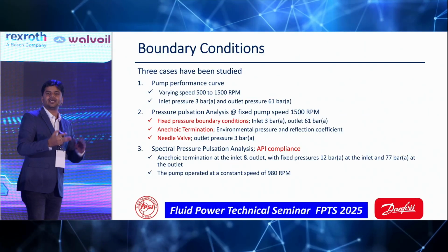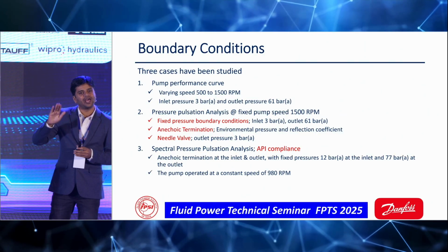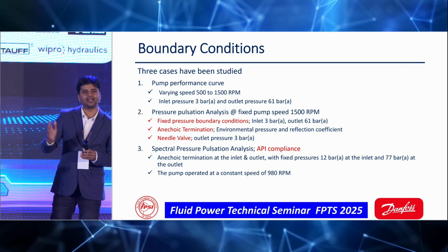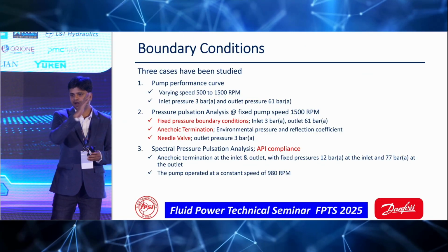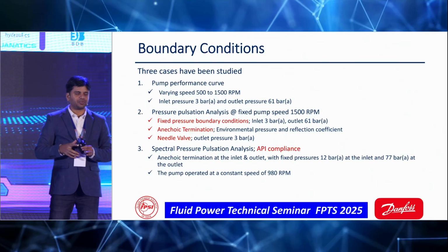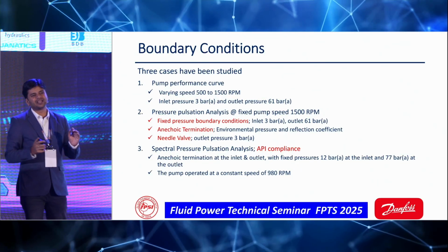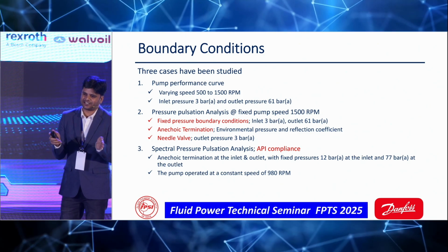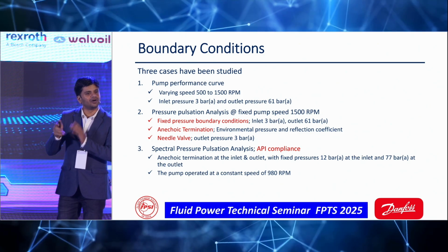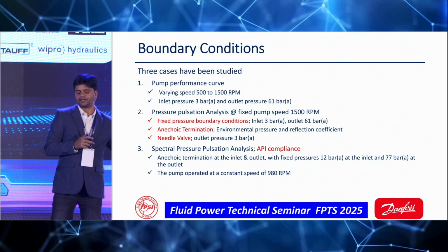The second case is that you can mathematically model these pressure waves so that you tell it there will be no reflection coming back. Everything smoothly propagates into the discharge pipe or inlet pipe. So that is the second case we tried. And the third case is mimicking the exact case in the test. In the test, you have a pipe and then you have a needle valve, right? So exactly the way we have done it.